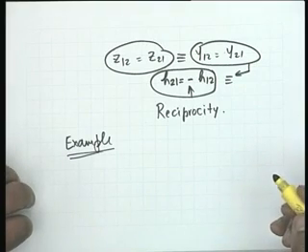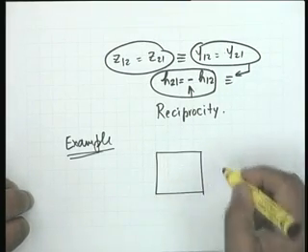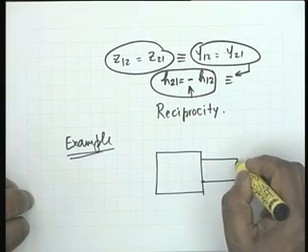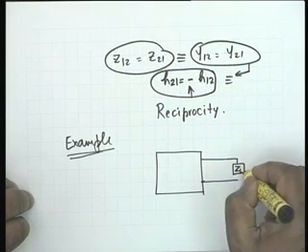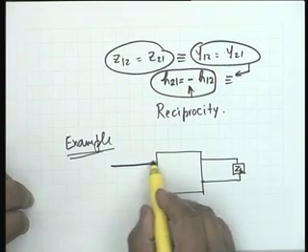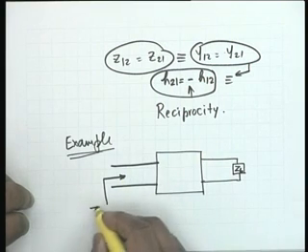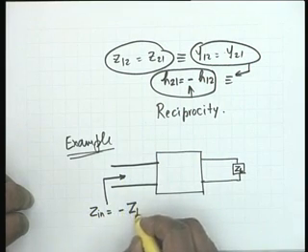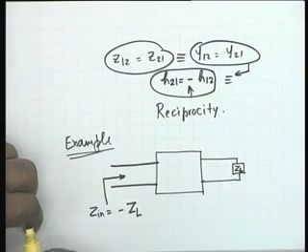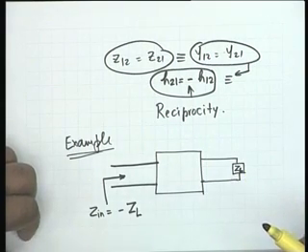And this example is that of a two-port having the particular property that whatever load ZL you connect at port number 2 reflects at the input as the negative of ZL, that is, Z in equal to minus ZL. Which means that if you connect a positive resistance here, it will reflect as a negative resistance, and this is the way to make negative elements.